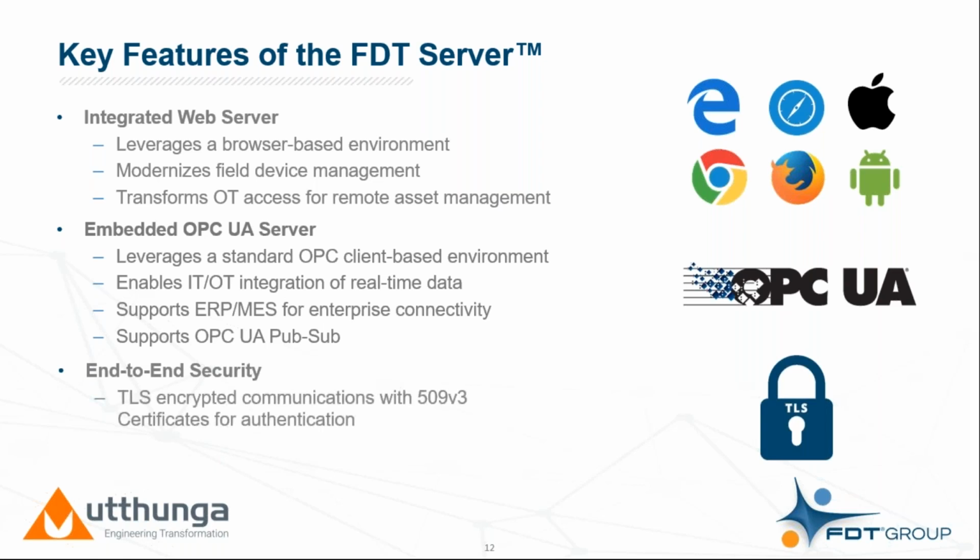We have end-to-end security in the model. It would perhaps be tempting, when you're working on a security model for an architecture, to come up with some new security standard, but we recognize that there are some very well vetted, very well accepted security standards out there in the industry that are accepted by both the IT side and the OT side of the organization together. The number one open standard for that is what's called TLS. This allows authentication of devices, of people, of servers, as well as encrypting the communications that get established through that.